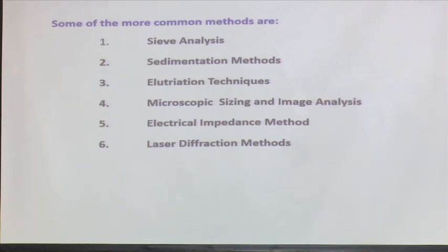Okay. Some of the more common methods that we adopt are basically sieve analysis, which is most frequently used in our industry. Sometimes for very fine particle processing we use laser diffraction methods. These are the methods which are available, but I do not think most mineral processing laboratories use anything other than sieve analysis or laser diffraction, or maybe a combination of these. In most cases, the plant people in their laboratory also use this, but for on stream analysis and for controlling the process, they are now using image analysis based systems. Okay. There are some professional versions available, but I am not going to mention them here because I cannot market their software and techniques.